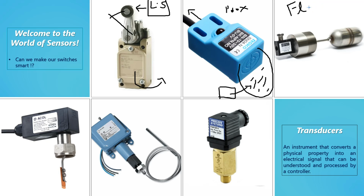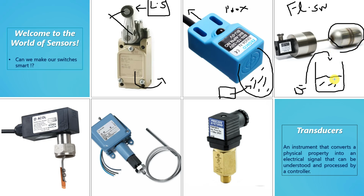Now this is a classical float switch. Float switches are one of the many devices used for level control, right? And how they work is pretty simple. The liquid is in the column, right? There is a pump and the pipe inside the vessel. Now this part here should be lighter than the liquid being used, right? So you install the float switch like this, and if the level is lower than the highest possible level that you require, the device will float on top of the liquid like this. As the liquid in the vessel rises, it will reach its desired height and will generate a signal when it reaches this point. So we will have a float switch working like this.